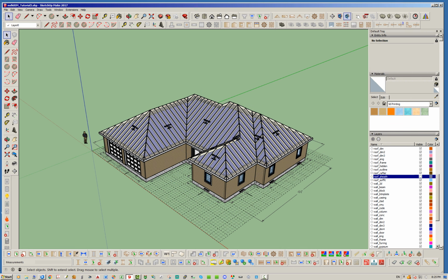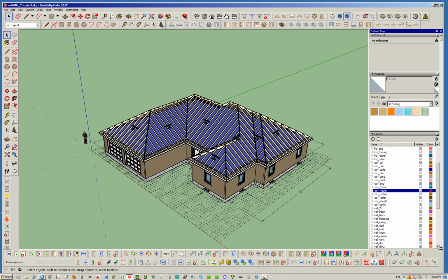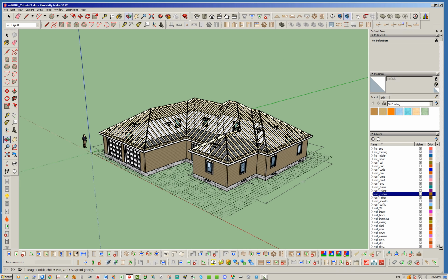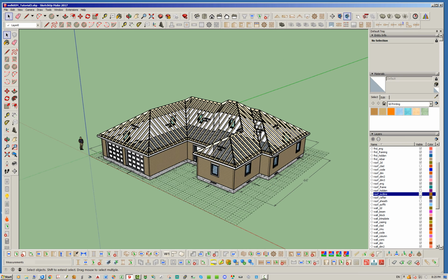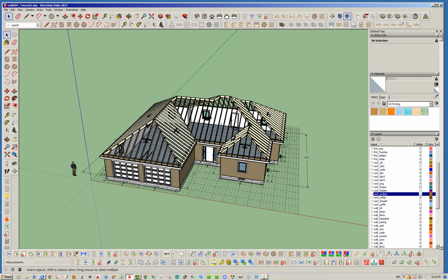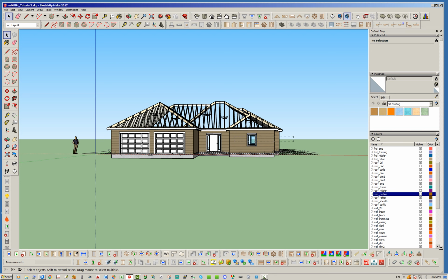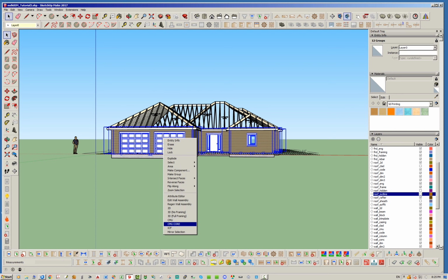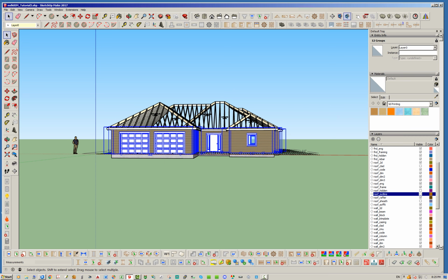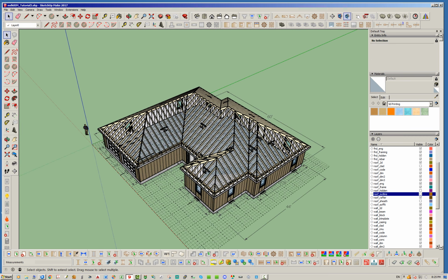And let's turn off the roof hidden layer, which is that primitive, and also the roof outline we want to get rid of. All right, and then with these walls, what we can do is grab a bunch of them, and we can go full framing on them all. Full framing. Give it a second to update. All right, so now the framing should be in there, and it is.